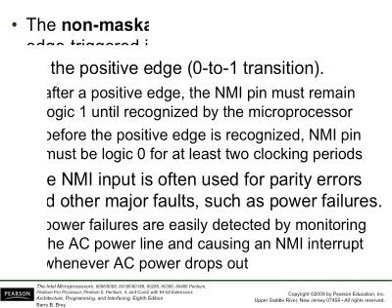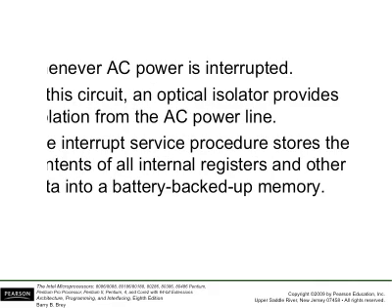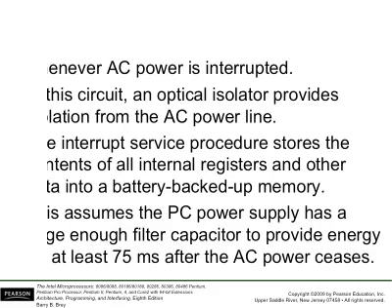Typical usage of NMI is for parity errors. For example, you have parity errors in your memory subsystem or other major faults, for example, power failure. In the next slide, I'm going to show you a power failure detection circuit that will provide logic 1 to the NMI.